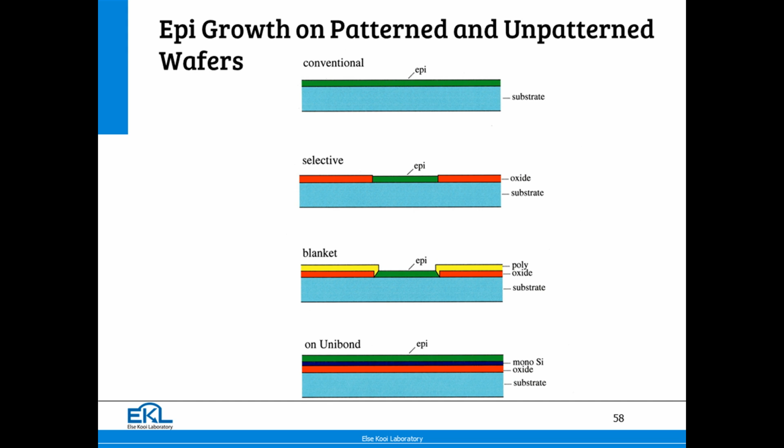And we got a hunch, well, we're running selective epi. We saw all sorts of growth rate variations that we could not explain, and we thought we were bothered by loading effects. And at some point in time, with an almost identical mask, we saw a difference, so it cannot be loading effects. What else can it be? Emissivity, maybe. How do you compare that? Well, these two are not on a wafer like that, because you're growing poly here, and you're growing poly thickness to epi thickness. It's not a good comparison.